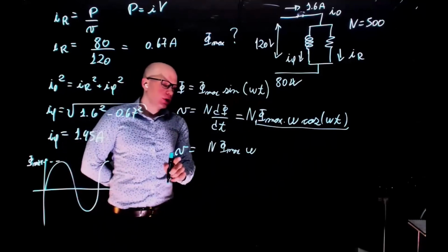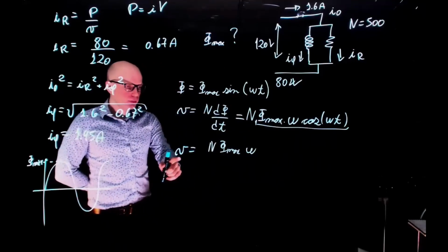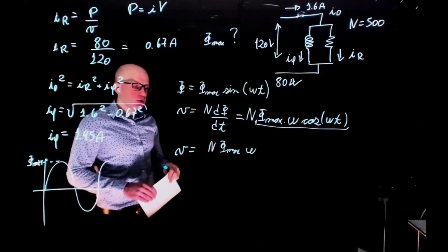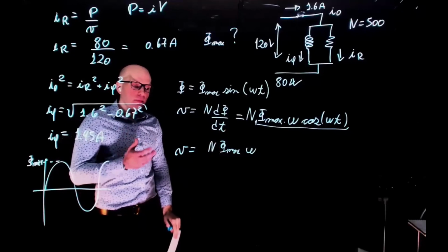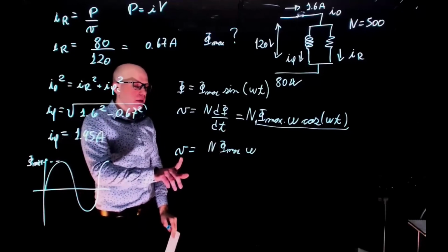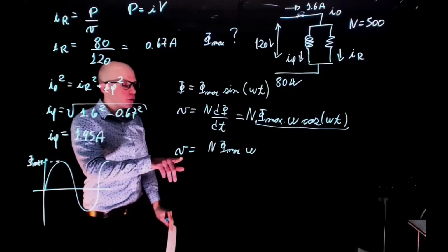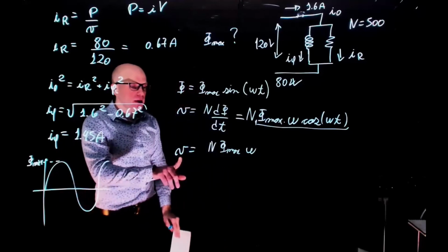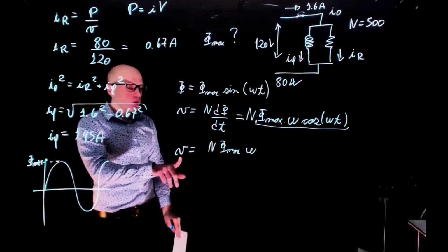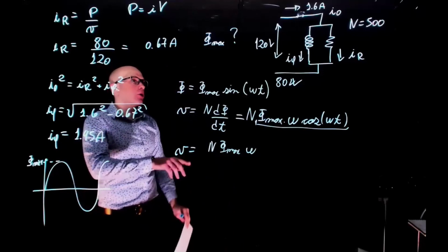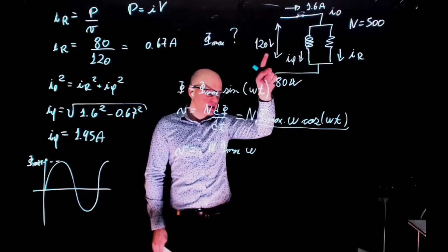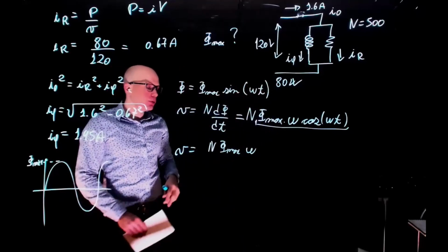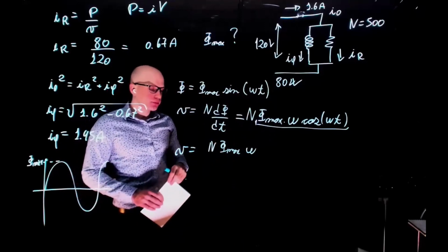Now this voltage here is a trick. Everything that we did with regards to transformer rating was with respect to a RMS voltage. So this is not the RMS voltage. This is the peak voltage. Because you're dealing with peak magnetic flux, we need to find the peak voltage in the transformer. But our ratings here, when you talk about AC and transformers, are all done in RMS, root mean squared value of the voltage.